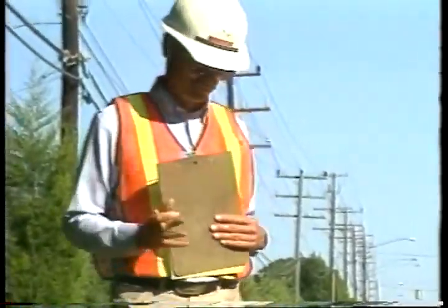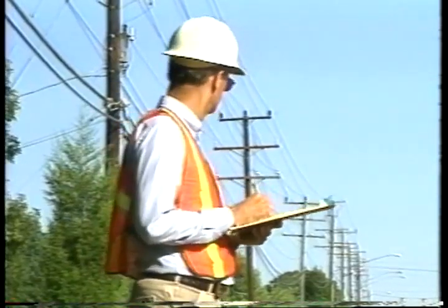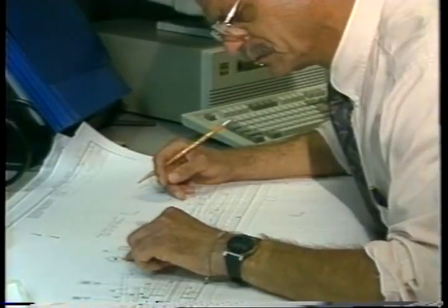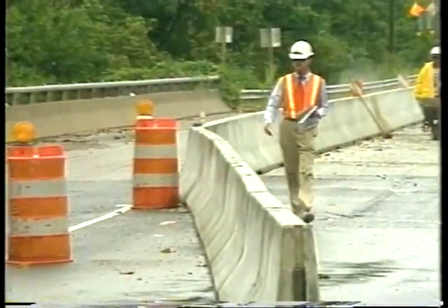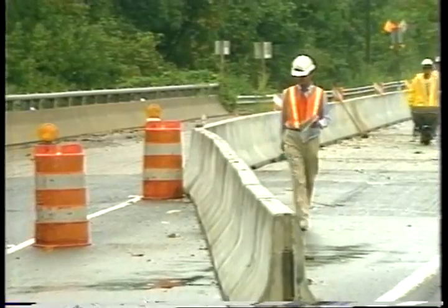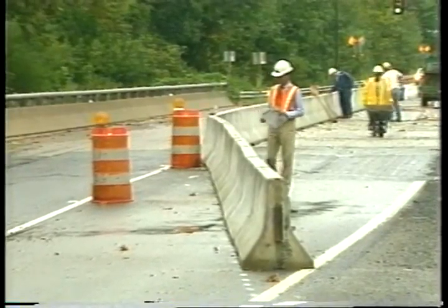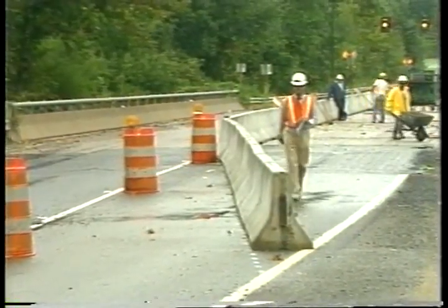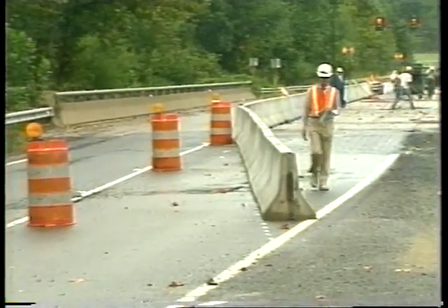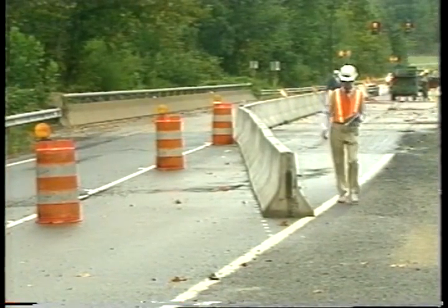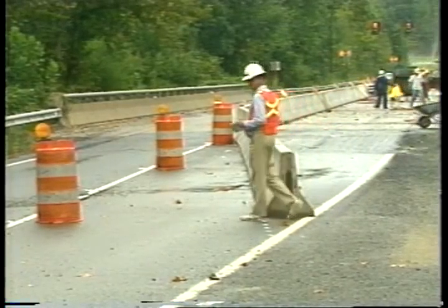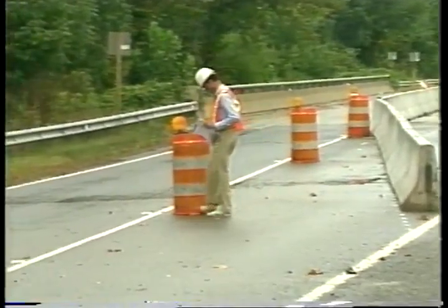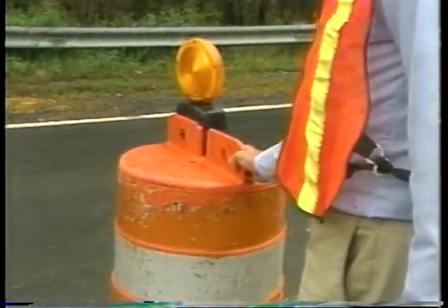We will follow the process from pre-planning through the actual design and writing, the implementation, evaluation, and even revision. Each step in the process is important. The plan includes traffic control strategies, staffing requirements, use of specific devices, and the design of geometric features such as tapers. In short, it is a blueprint for handling traffic through the work zone.